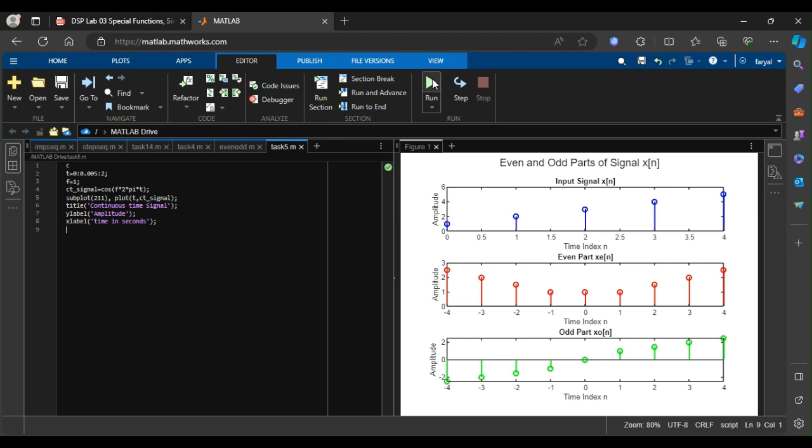And the second part is we plot the continuous time signal in the first plot. We multiply the continuous time signal with an impulse train to obtain the discretized signal. Then we plot the discretized signal in a second subplot. This discretizes the given continuous signal using an impulse train for sampling. Adjusting the sampling frequency fs allows you to control the level of discretization.